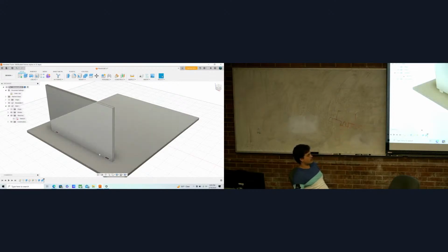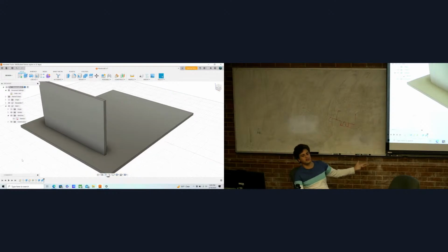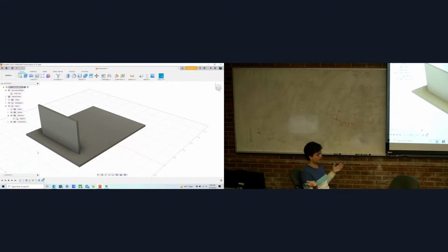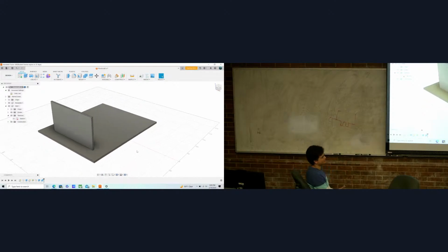because we originally defined it to be relative to this edge, right? Also, if I hide this, the positions of the 2 holes have changed. Because along the way, we did a good job of constraining everything properly, if we go back and change some critical dimension in the timeline, everything else just updates on its own. We don't have to go back fixing a million things. If you didn't, then you probably would have to go back fixing a million things. So try and stay on top of making sure that you're dimensioning things along the way.